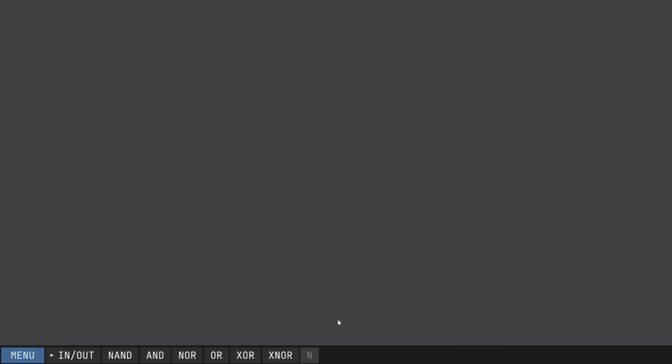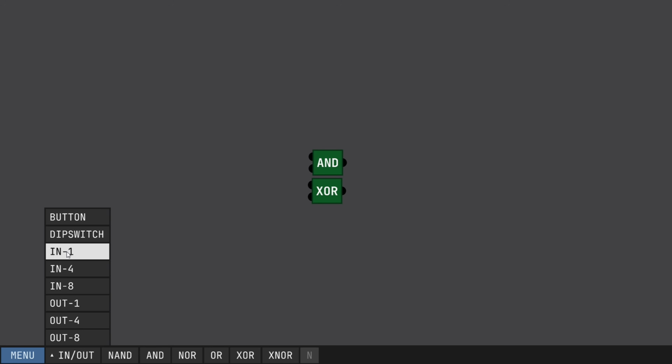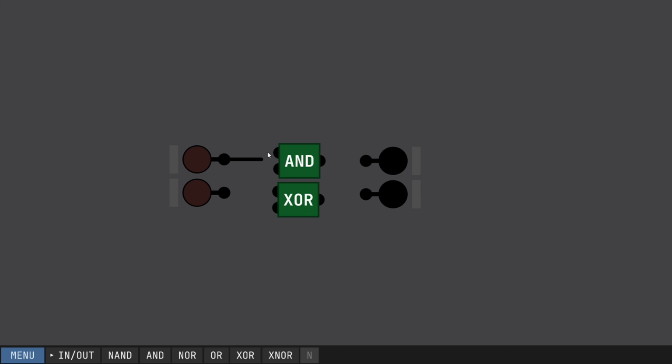So if you remember from our Blender simulation, we kind of discovered that all you need is an XOR gate and an AND gate, and you can make two numbers be added to each other. So that's exactly what we're going to do right here. So we hook these up to each of them, and then we hook the outputs up. This is going to be our carry, and this is going to be our sum.